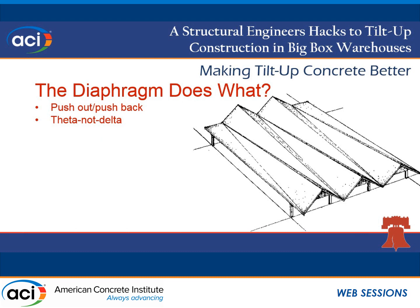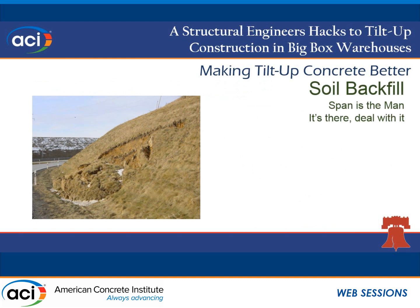But the other thing is thinking about your load path, especially in a seismic world where you maybe have, on the West Coast, a hybrid wood roof. Thinking about your sub-diaphragm action and all your connections. Just make sure that you've got your entire load path in your panel design: out of your panels, embeds, into your joists, joists into the diaphragm, diaphragms into the sub-diaphragms. So make sure you've got a load path, right? That's the first law of structural engineering.